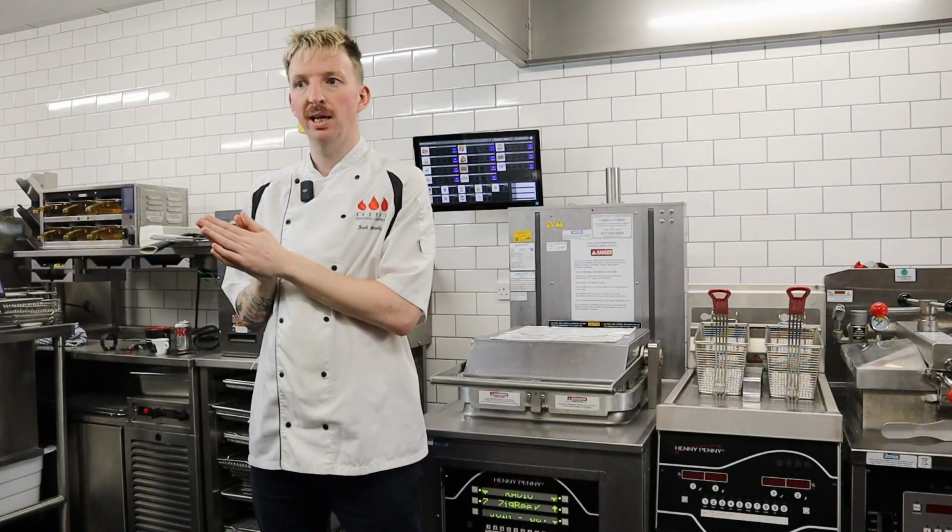So to summarise, if we look in our info screen and we can't see our radio options, we might need to do a software update. If we can see our radio options but the radio is off, let's turn it on either in data communications or in special programming. If we're looking at our radio panels and we're getting lots of Fs, that means there's continuity between the radio and the controller. We just need to help it join the network. So let's do some network resetting from the touchscreen. If we're getting lots of zeros, we haven't got continuity between the radio and the controller. And let's look at the radio and the connections there.